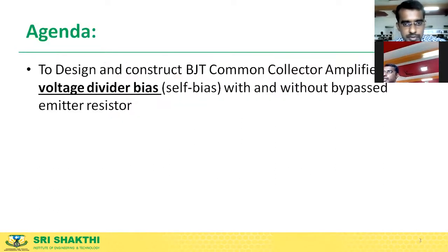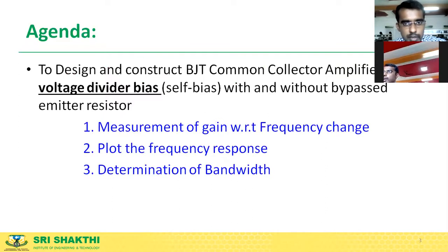The agenda of this experiment is that we need to design a common collector amplifier, especially using self bias or voltage divider bias. Then we are going to measure the gain and the bandwidth. We are going to plot it on a semilog sheet and find out the bandwidth. So that's the agenda. Let's move on.